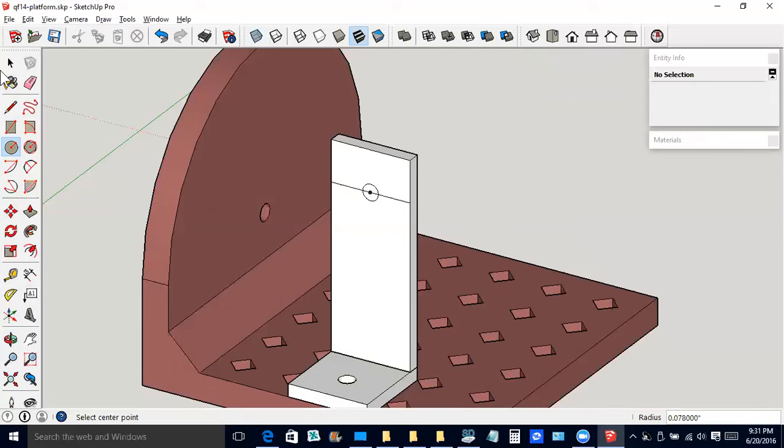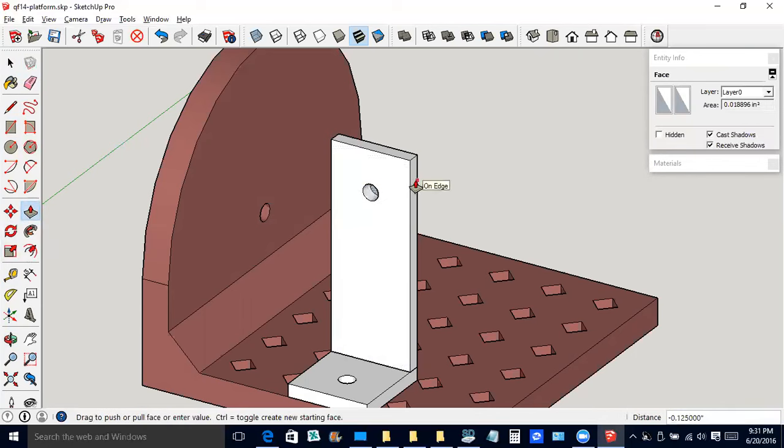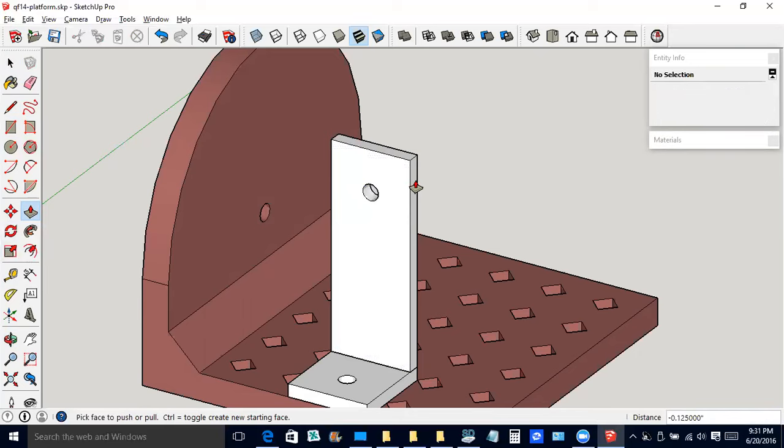I'll get the eraser tool over here. And the part that we want to erase is inside that little circle on the lower left, well, the corner of the eraser tool. Push-pull tool over here. We'll pull this thing back over here like so. And notice I stopped with the point of that red arrow on this line here. That's telling it that when it makes the hole and it gets to this point, the plane that this is on here, it'll stop there.